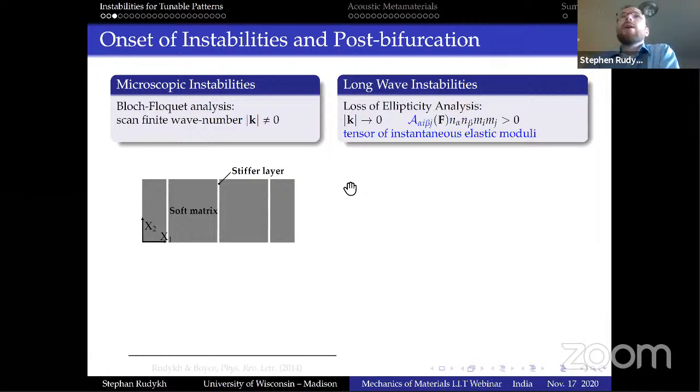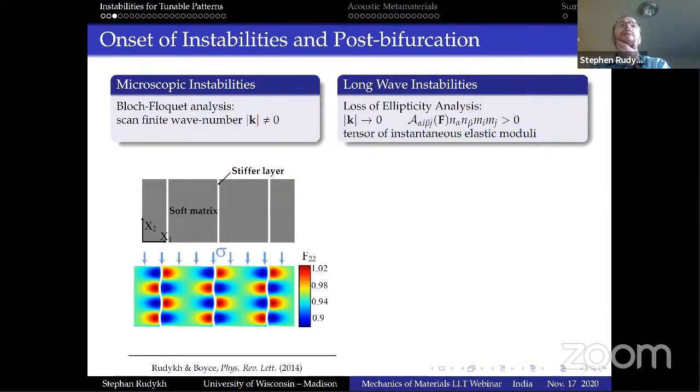Behind that is a very solid and rigorous theory, which I omit here for the sake of time. We perform this analysis in some cases analytically, and in some cases it can be implemented in finite elements. But in this way or another, we obtain the information of what happens at buckling and what to expect the material to develop after buckling. That's where we go into the post-buckling analysis, to help finite elements find these patterns.